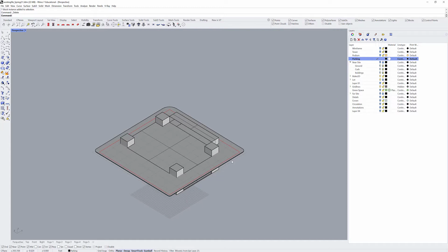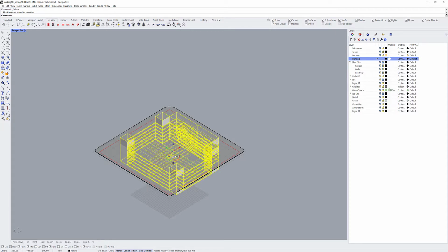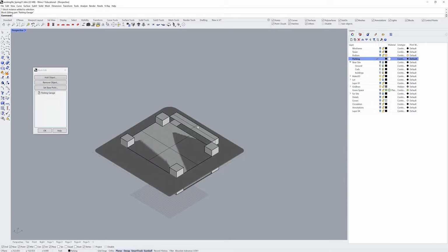actually one more thing. It's about layers. So whenever you insert a block, it has layers sort of inside that file already. So if you have the same named layers, it will actually go onto those same layers. So in this file I already had a parking layer, so all of this stuff was adjusted to the parking layer. Now you have to be aware that the geometry inside the block can be on a different layer. The block itself is all on the parking layer, so if I select the block, you can see it pops up as parking. But if I edit the block and I change this to, say,